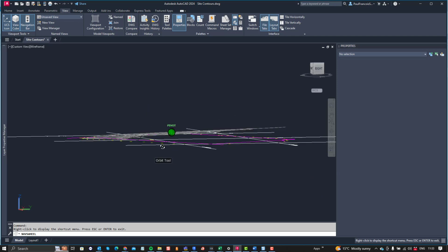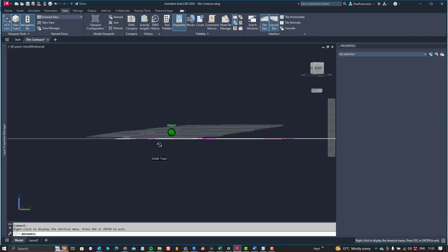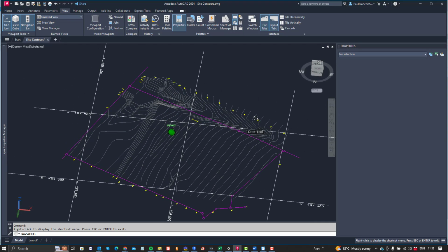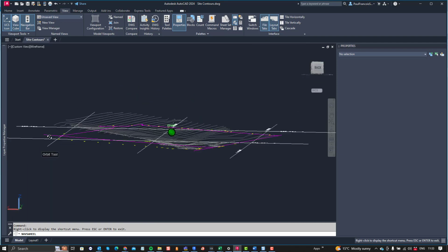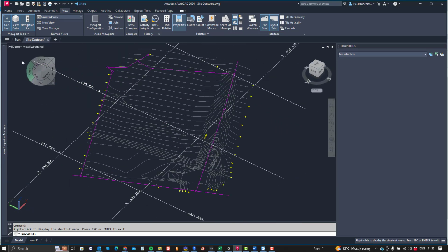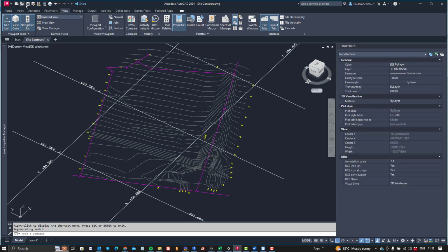Here we can see that the contours are in 3D, and that's what we'll use to generate the topography. So if you can get your surveyor, or if you yourself can set up a file that looks something like this, that would be perfect for bringing into Revit. Reference to a real world origin with the real distances away from the origin, and then also in the vertical.